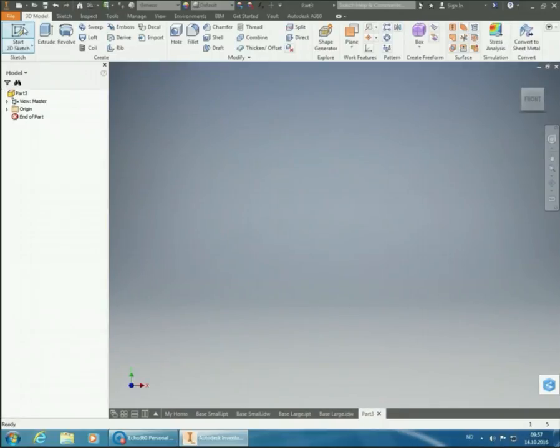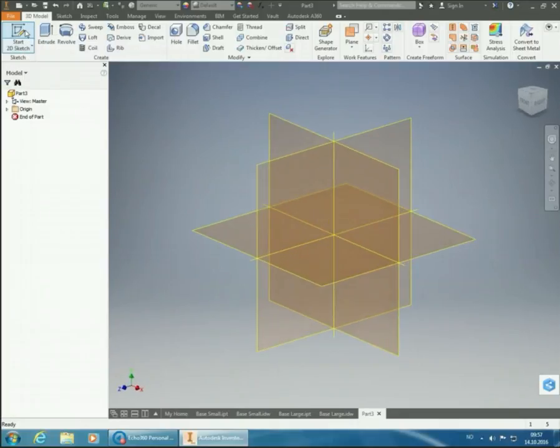And I mentioned briefly when I started the previous part that for this one I'm not going to choose the horizontal plane, because I'm basically going to create it like this in the planes here, but I want to do this outline when I'm drawing it, which means I'm going to choose the plane that's going vertical along the Z and Y axis. So I'm going to place my sketch there.